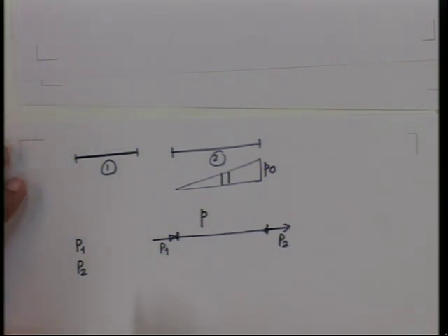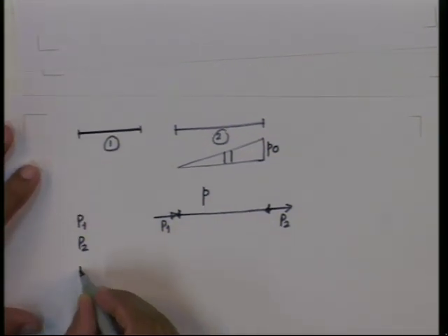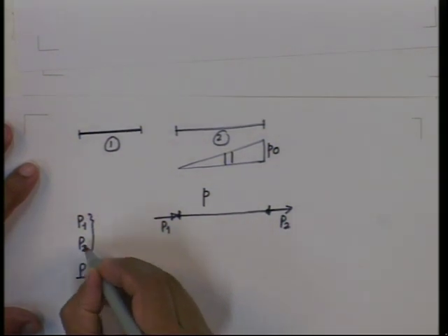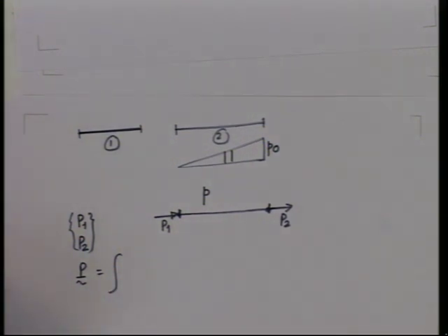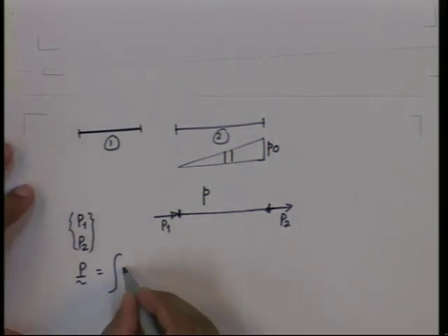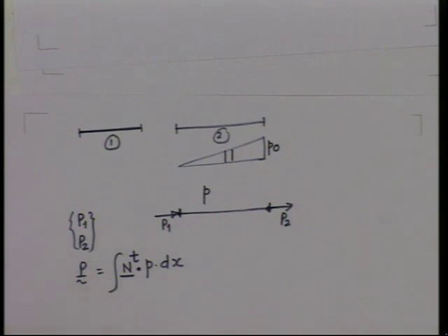What are P 1 and P 2 given by? Yes, very good. If you combine these P 1 and P 2 into vector P, we also give that as integral of Ni transpose P dx. We can also write a general formula: instead of Ni Nj, I can write N transpose.